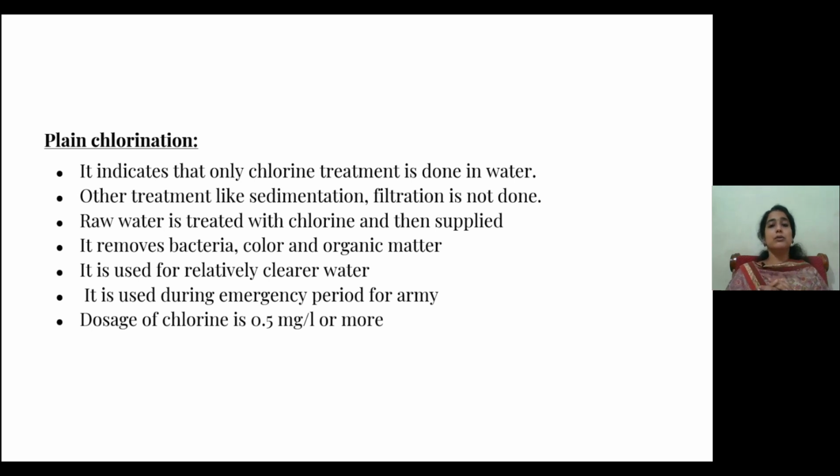If we are not doing all these treatment systems, we can accept plain chlorination if the water is clear, that is there is no visual pollution, and there are no impurities entered into the surface water, then we can adopt this. And in the case of war or any emergency situation, we can accept plain chlorination.